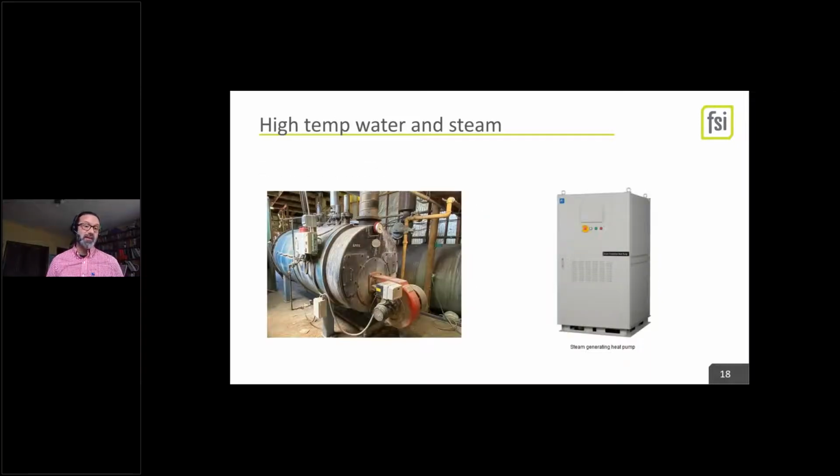We got to talk about... go ahead. There's one actual comment here, which is heating coil replacement can allow low temp heat pump replacements. Correct. Yeah. So if you've got particularly built up air handlers, coil replacements make a lot of sense for that large system. You can replace all your terminal equipment. You could keep your air handler fan and just replace the coil. You could replace all the radiators. You could keep going down the line.